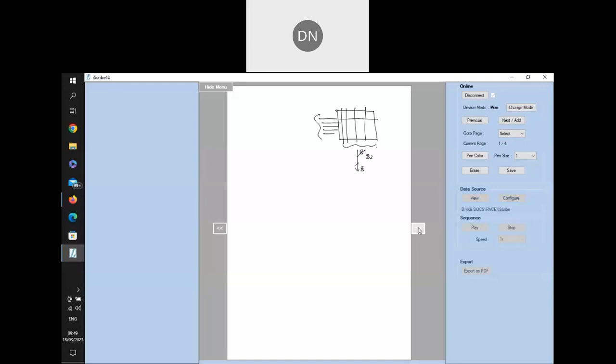In such cases, a multiplexer will be used in the circuit. First a row will be selected. In that row the number of bits will not be 8, it will be more than 8. Let's say 32 is available, but my data bus is only 8 bits. So I will select 1 byte among the 32. That means a multiplexer will be used.